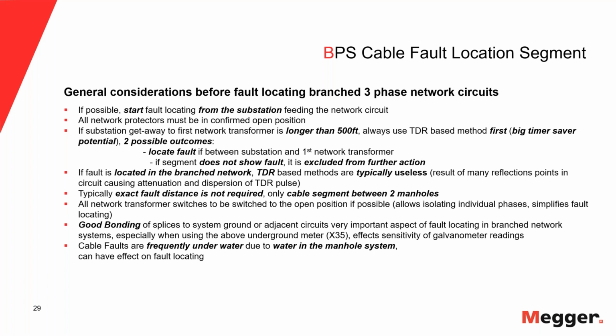But because you do it above the ground, the signal is already reduced. So you need a very high sensitivity signal unit, to pick the signal up. Now, if you have a poor signal, it could be that the unit won't pick up anything. And that's what I hear sometimes. People say, well, we use it, sometimes it works and sometimes it doesn't work. That is a clear indication of the bonding condition in your circuit. So I just want to point that out. It's not equipment.